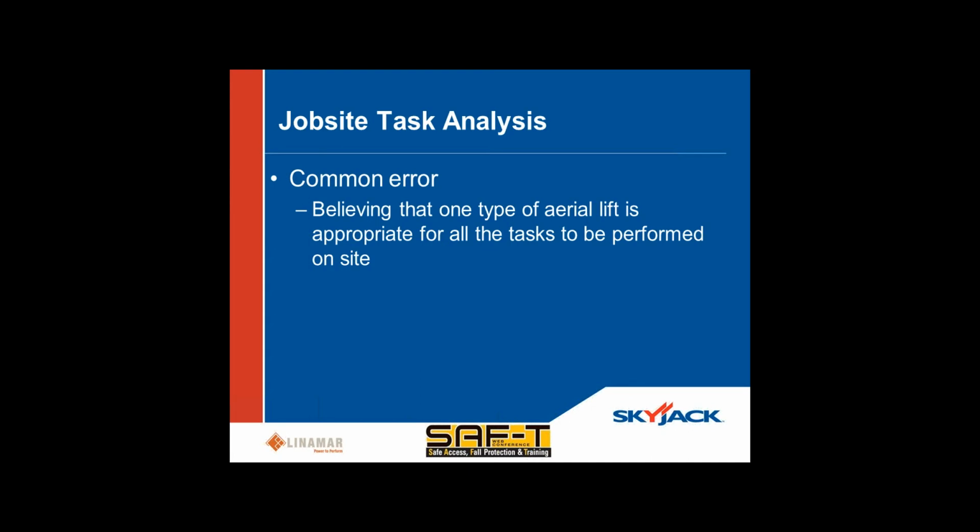And the problem is that it's not suitable for that last 5%. And people begin to improvise when they don't have the right equipment. And from a safety perspective, that's when they tend to get in trouble. So if you do this analysis properly and understand all of the tasks that you're going to need that lift for on that job site, certainly you can give your employees a better degree of safety or confidence that they do have the right piece of equipment.